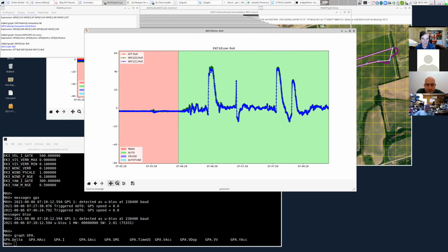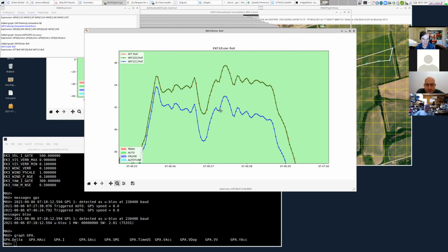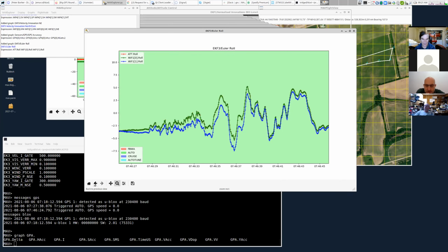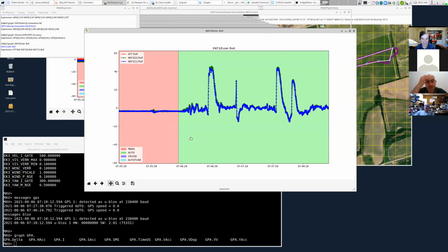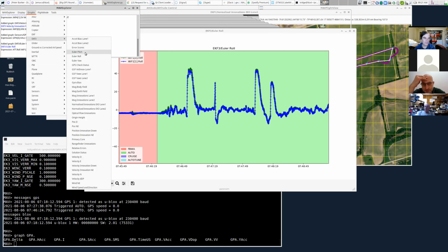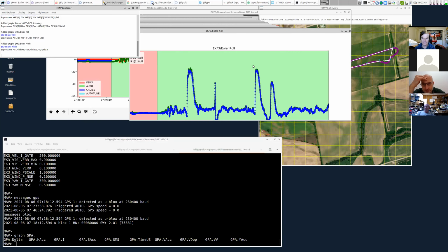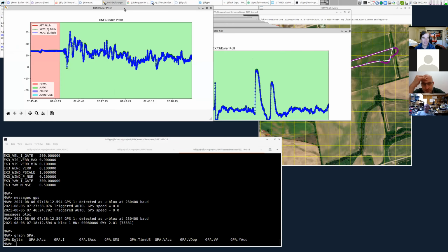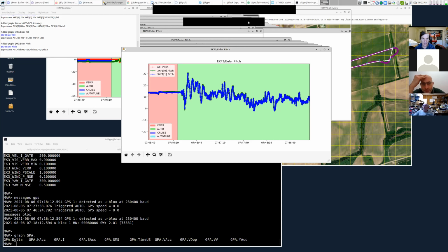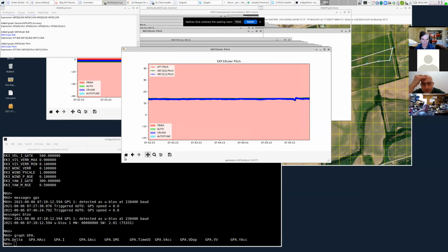There's a small difference here. In a sharp turn, we can see a difference of like 2 or 3 degrees. It's not huge, and that's not really uncommon. A little bit of difference here, again a degree or 2, so not really uncommon at all, particularly as they're not the best IMUs. The Pixhawk 1 was fine in its day, but is a little bit dated on IMU quality now. Let's have a look at the pitch and see whether they're nice and consistent. So here's our pitch estimate, and you can see again the 2 different pitch estimates. This is the overall one that it's using, and these are the ones from the 2 lanes separately, and we can see that they're pretty consistent. We don't have any problems.